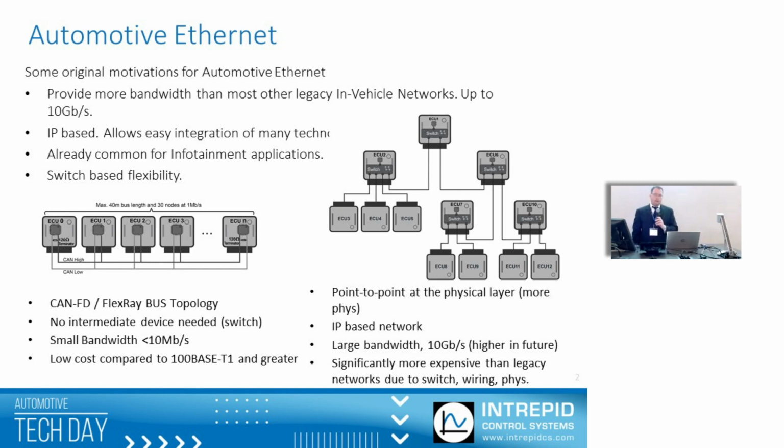So what's happened in the Ethernet world in general, you'll see a progression from the early days until now, is that speed grade has just been increasing, more speed. In the Automotive Ethernet world, the very beginning was 100BASE-T1, which is 100 megabits of bandwidth over a single twisted pair of copper cabling. Shortly after that, there was 1000BASE-T1, which is gigabit. We currently have multi-gigabit, 2.5, 5, and 10 available, and now we're even pushing beyond that, above 10 gigabit for Automotive Ethernet.